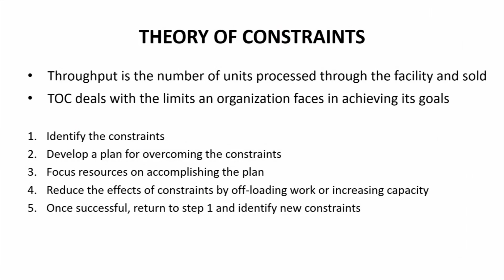And many times theory of constraint is also used in scheduling. We find out which one is the bottleneck stage. Rather than providing the schedules for all the processes in the sequence, we can identify the one which is the bottleneck. Suppose this is the bottleneck, this is the constrained resource. So, we schedule it only. The pace of the complete line is decided by that.